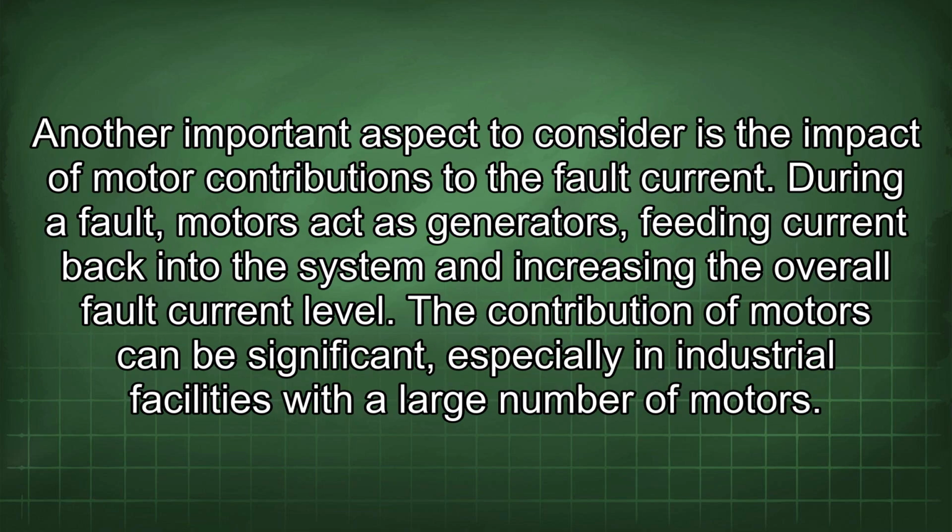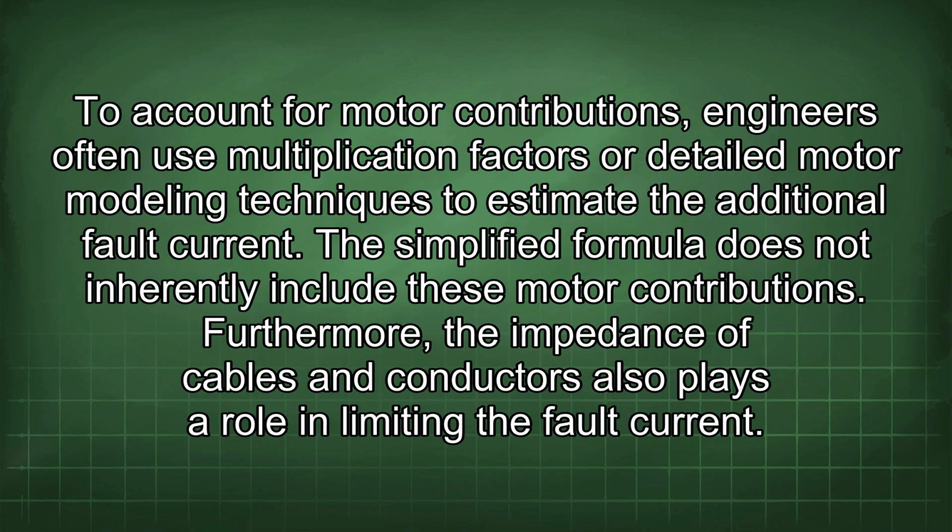Another important aspect to consider is the impact of motor contributions to the fault current. During a fault, motors act as generators, feeding current back into the system and increasing the overall fault current level. The contribution of motors can be significant, especially in industrial facilities with a large number of motors. To account for motor contributions, engineers often use multiplication factors or detailed motor modeling techniques to estimate the additional fault current. The simplified formula does not inherently include these motor contributions.